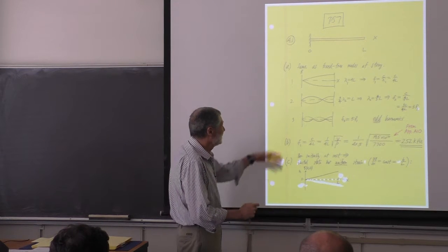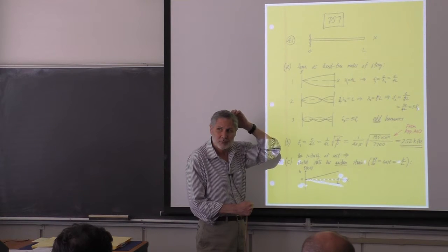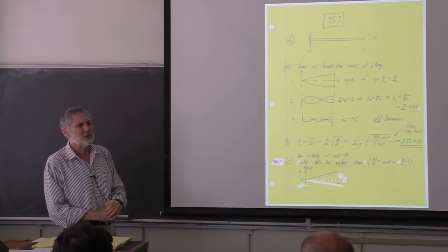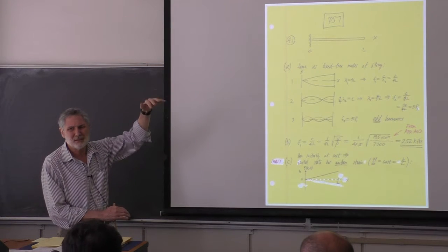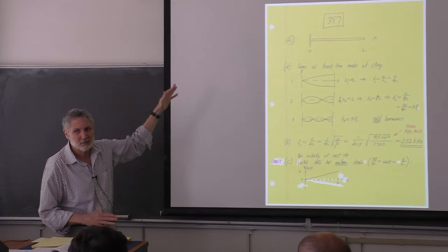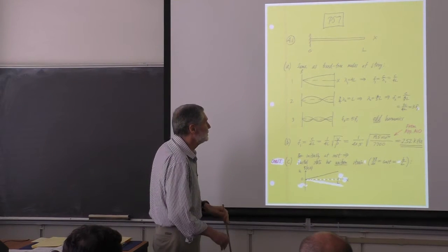The same thing's going to happen in acoustics for sound in a pipe. And that's why I launched off into the organ pipe thing. Remember, blocking the end of it? Kind of counterintuitive, right? If you have an organ pipe, why would you block the end of it? Well, you could save yourself a lot of length if it's a very deep bass note. Lower the frequency by a factor of 2.